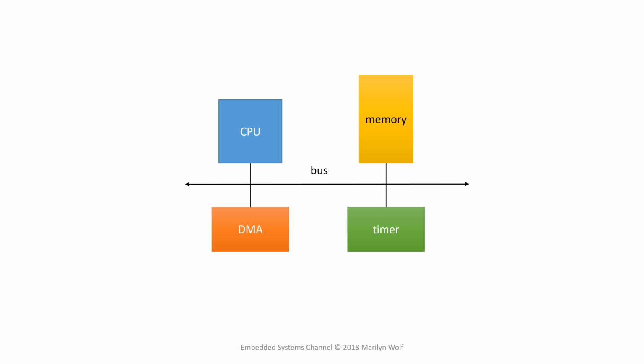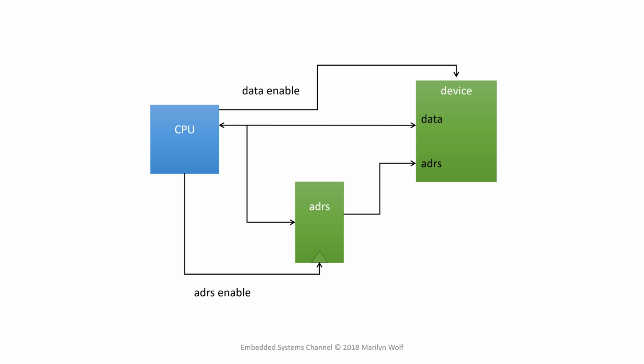In most cases, the CPU acts as the master of the bus. It controls the bus operation, sets the bus control signals, and determines when things happen. If DMA is to perform independent transfers, it needs to be able to become bus master. So it uses two signals in a 4-cycle handshake to request bus mastership.